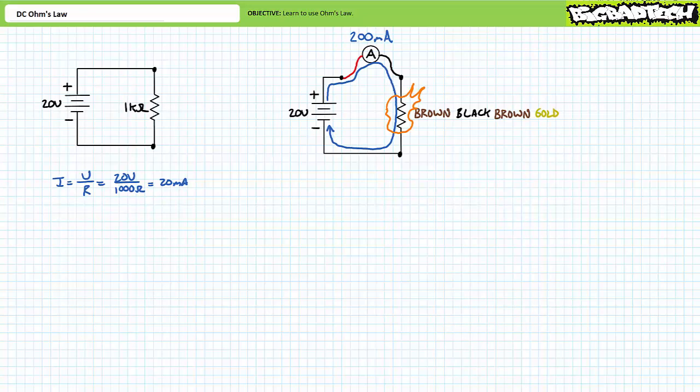Never trust them. A 100 ohm resistor provides substantially less opposition, 900 ohms less to be exact, than the specified 1 kilo ohm resistor. An application of Ohm's Law demonstrates that the smaller 100 ohm resistor with a 20 volt differential across it should experience 200 milliamperes of current, i.e. 10 times greater than what we anticipated. No wonder it burst into flames. Ohm's Law says current will be high for low resistance paths.